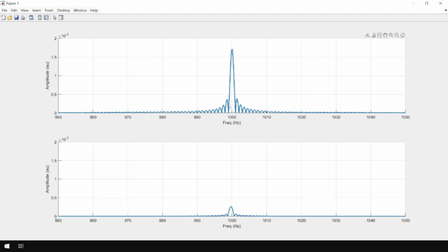So once again, you can see this sort of perfect sinc function, and clearly this is the 1000 Hertz excitation, right? However, if you look at that peak, that isn't actually on 1000 Hertz, and if you look at this peak, it's quite visibly off. Now that's a problem if we're going to subtract these two data sets to try and actually determine the gain.